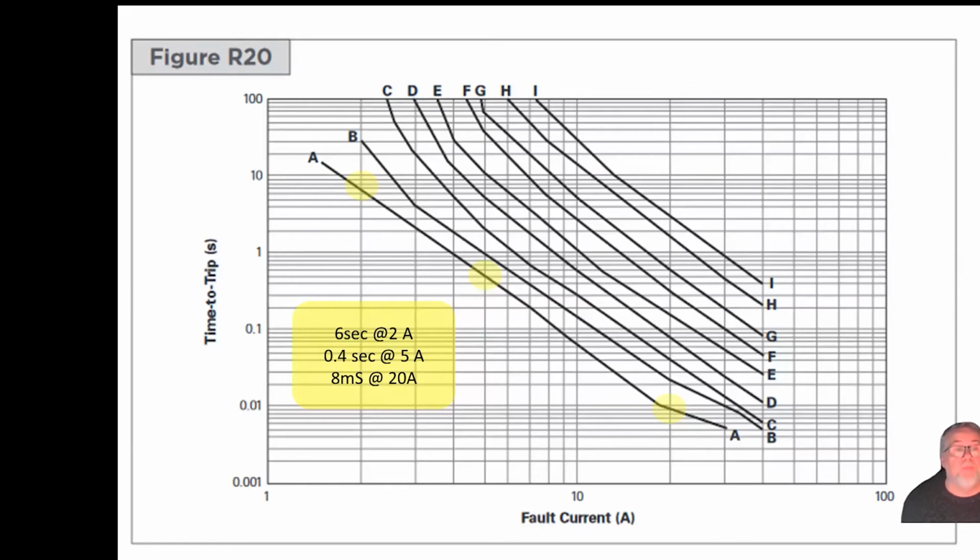This is taken from one of the data sheets from the Polyswitch Manual, and I've highlighted 3 spots. This is one of the low voltage ones. This is a 6 volt Polyswitch, a 6 volt semiconductor fuse. One of these ones that I'm telling you, you can just put onto your board. It's a 1 amp fuse or a 2 amp fuse, I think.